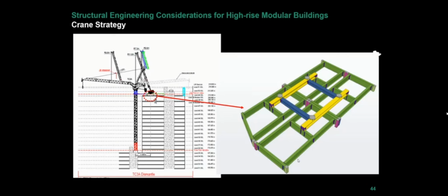So for the first time, we installed what's called a derrick crane on top of the modules to remove the remaining tower crane. That had a few challenges in that the forces were still up to 300-400 kilonewtons per leg in this crane, and it was sitting on module posts 40 stories high. So there was quite significant axial compression, or axial shortening, which was significantly overloading the module posts, the local module connections. So we came up with a grillage design, which is actually 4 modules.